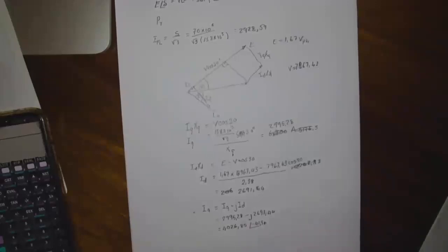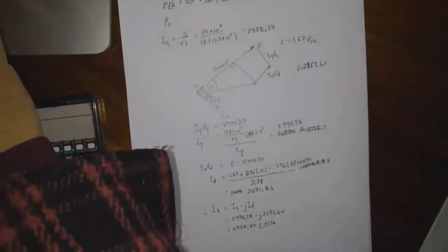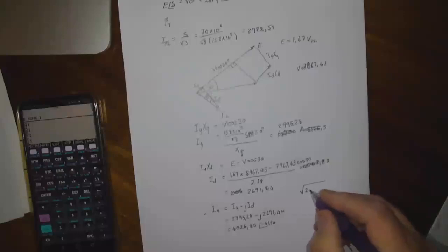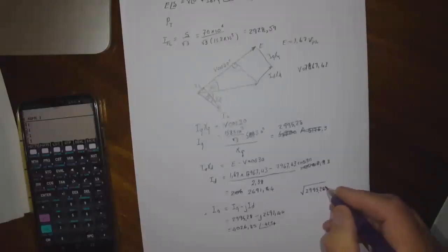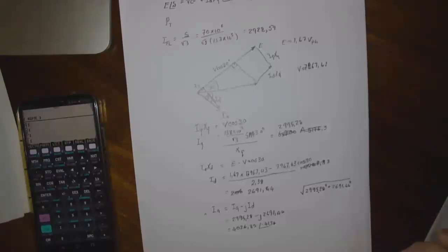Right. Now we have to calculate the power. Sir, can you use another method to get IA? Because I want to double check something. Can you use one of those two formulas: ID equals IA sine of power factor angle plus load angle.